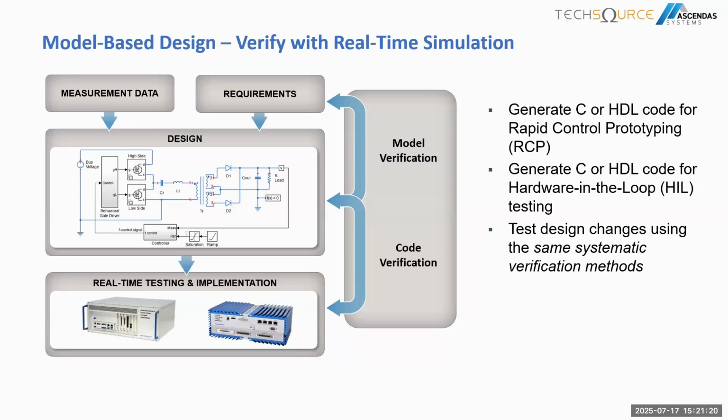The second option for generating code for electrical systems models is known as hardware in the loop. This hardware in the loop helps us engineers test our control algorithms not only in the model in the loop only, but you are also able to emulate the actual electrical system in this case, and test your systems so that you can avoid building the hardware, which is very expensive.